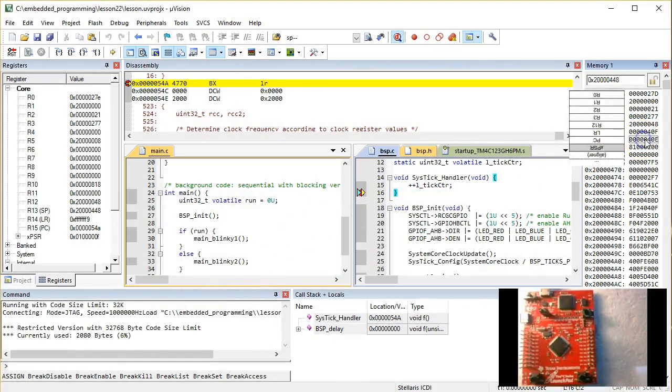I will then align the interrupt stack frame with your stack memory view, remembering to flip it upside down because the ARM stack grows toward the lower memory addresses. As you can see, the 7th stack entry from the top contains the program counter, PC. This value will be loaded to the PC register upon the return from the interrupt.